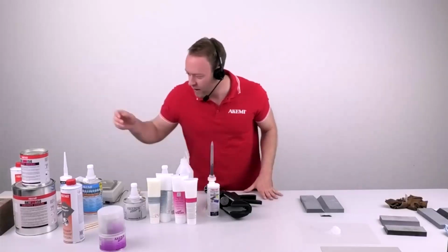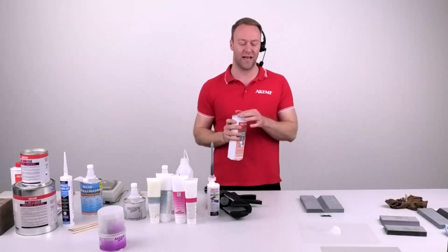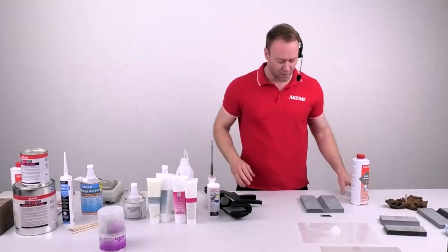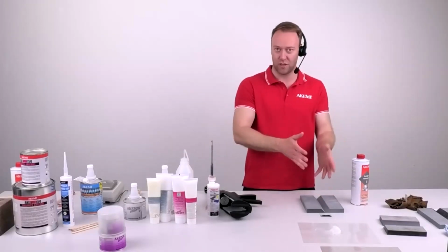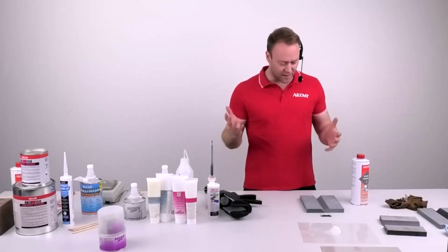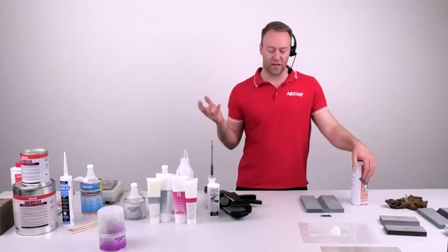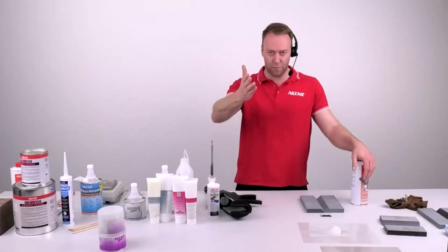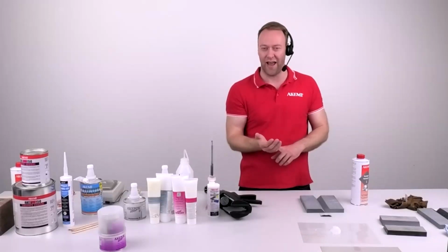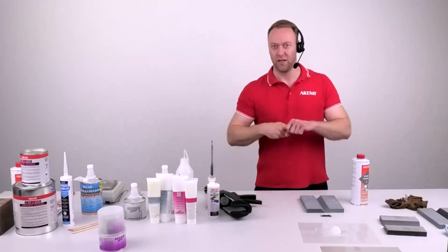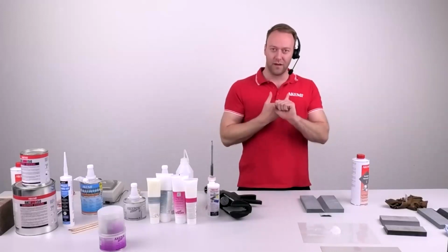Yeah, we clean. And what do we use for cleaning? We use alcoholic cleaner, like our cleaner eye. We don't use acetone. Why don't we use acetone? Of course, it removes grease and remaining humidity and maybe also some glue and some dust, but acetone evaporates extremely fast. That means, probably all of you know, stick a finger into acetone or get a drop of acetone on your hand, it will be really cold, because of the evaporation energy, your finger becomes very cold.